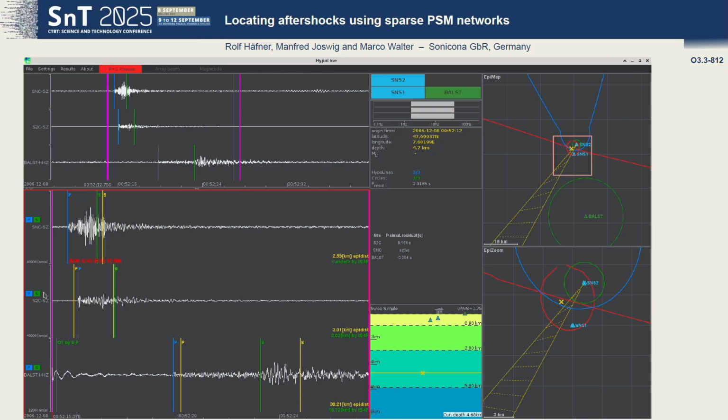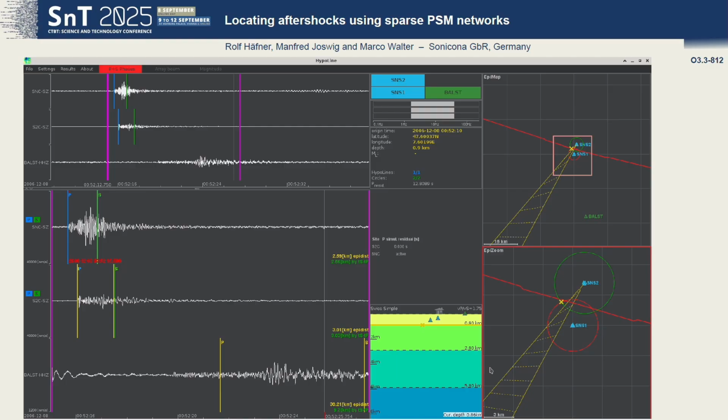This is this circular-looking hyperboloid section that is introduced here. But I removed this pick for my final interpretation because at this point we really can't be sure about the velocity model, and if we are spanning larger distances, we need more information about the structure of the lower layers. So let's stay at our two stations.